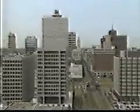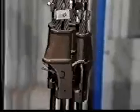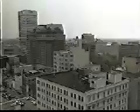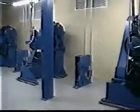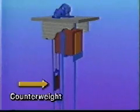The high-speed traction elevator has no limit on height, so it's a natural for high-rise buildings. The traction elevator is pulled up by cables attached to the top of the car. The machine room is normally located above the hoistway in an area known as the penthouse. This machine room is where the driving machine for the traction elevator is located. Cables or wire ropes run from the machine room down to a dead weight in the hoistway called the counterweight.